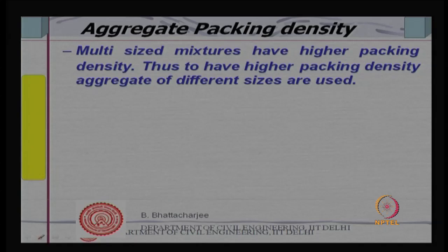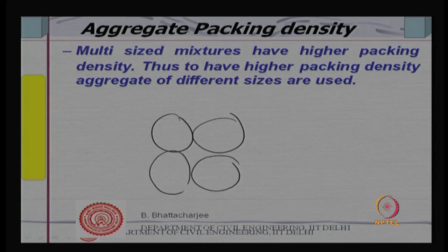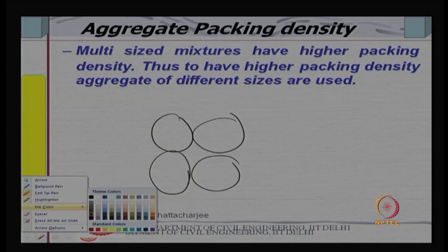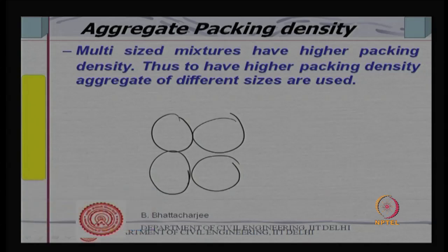How is it? Let us first look at it simply. Supposing these are my particles and they are packed, let us say again in simple cubic packing. Now, let me put another aggregate, finer, in between. In that case, the void of the aggregate packing will be reduced.